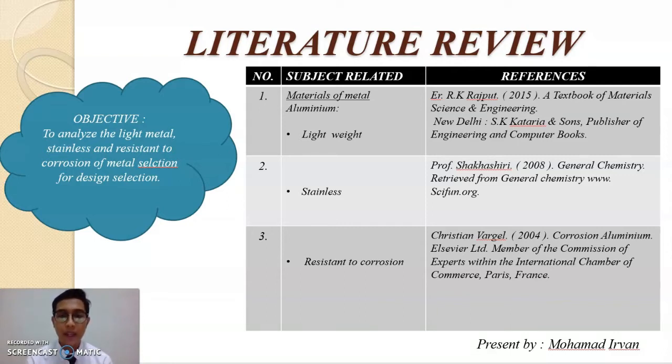Aluminium has a good resistance to atmospheric corrosion. Aluminium and the alloys of the 1000, 3000, 5000, 6000 and 8000 series have excellent resistance to atmospheric corrosion in the marine, urban and industrial environment. This very good resistance to corrosion, as much as its lightness, explains the development of numerous aluminium applications.